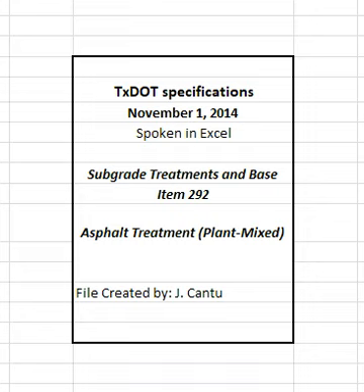4.4.3 Laydown operations. Dump and spread the asphalt mixture on the approved prepared surface with a spreading and finishing machine. Place the material without tearing, shoving, gouging, or segregating the mixture. Do not jar or bounce the finishing machine when loading it. Obtain the required lines and grades without hand finishing.